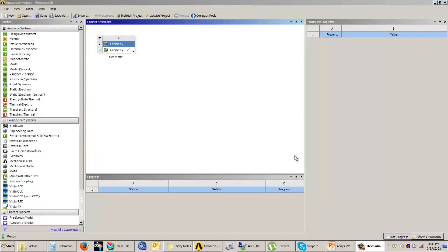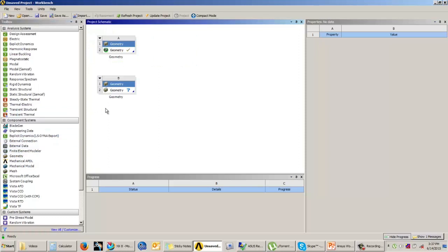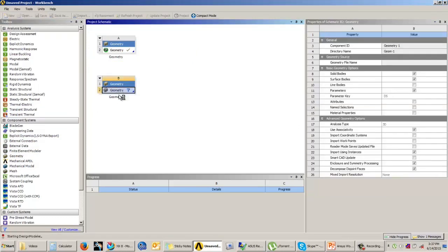Now let us understand the loft feature. In the loft feature, we can add material between two different cross sections or more. These cross sections can be different in shape and size, but need to be parallel to each other. So let us understand how to create this loft feature. I have added one new geometry, a standalone cell. Let us enter into the modeling, Design Modeler.